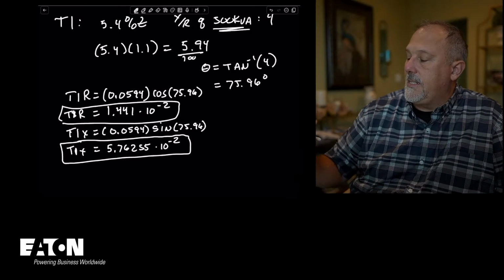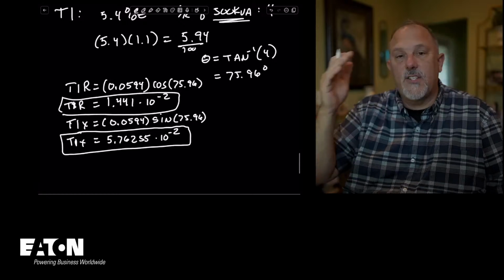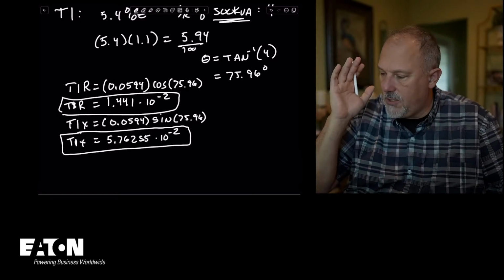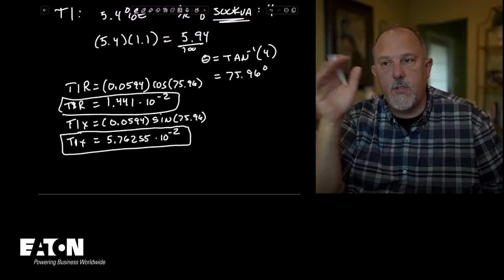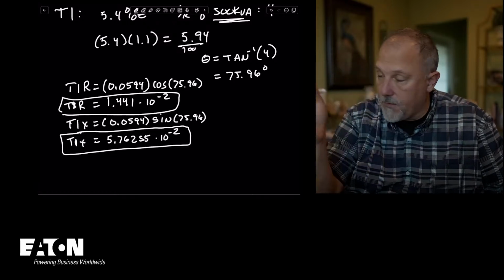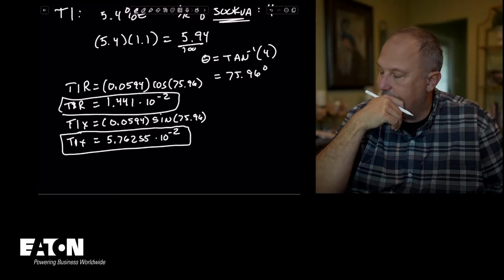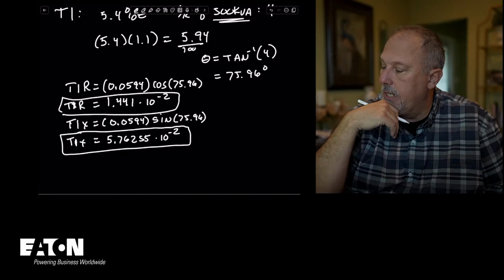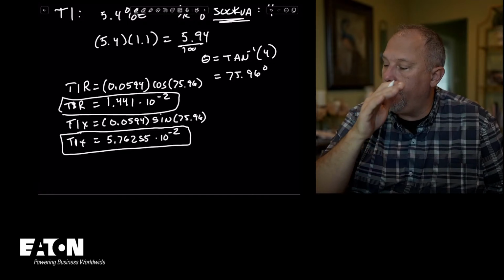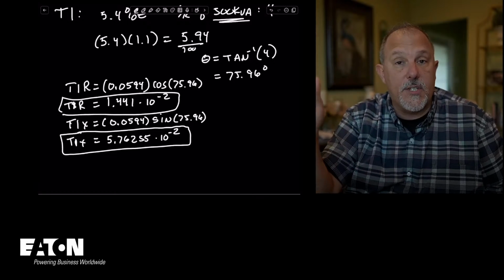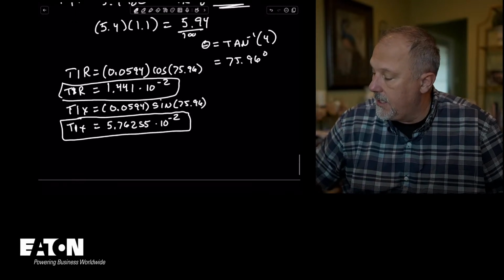All right, so there is the T1 transformer, and those are the real and reactive components for transformer 1. Remember, we took the X to R ratio from a reference. We used 4 for this 500 kVA transformer. We took the percent Z multiplied by 1.1. That increases it by 10%. That'll give us the lowest fault current. So there we have that.